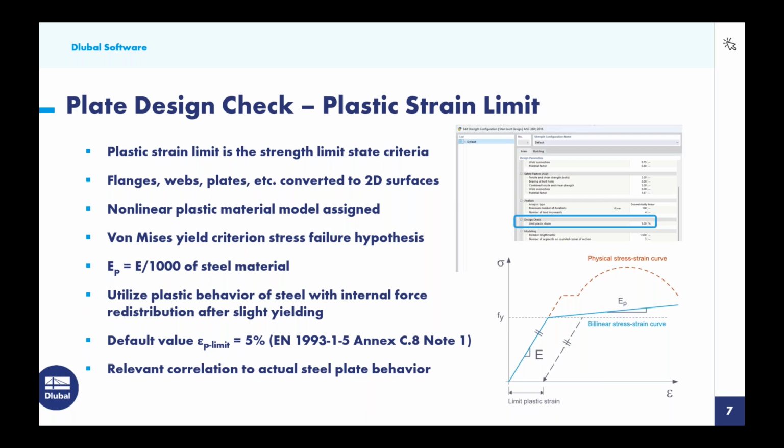when in reality, we know that if a single FE mesh point reaches this yield strength, the load is actually distributed to the FE mesh points around it. And as long as we don't have a huge region of the connection that is yielding, the entire connection actually won't fail when a single FE mesh point reaches that yield stress.